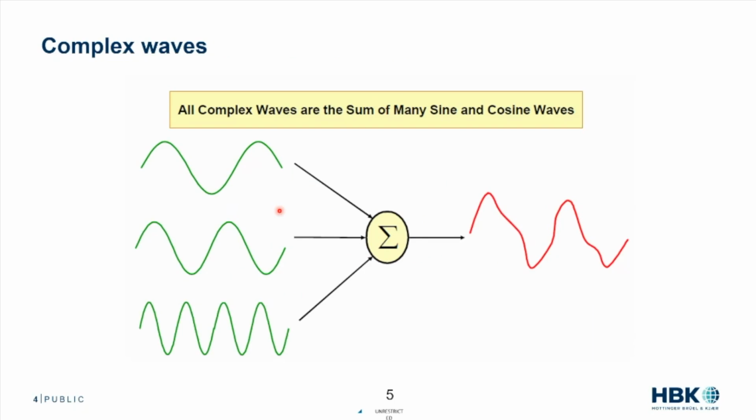So as many of you might know, electric motors have excitation that's sinusoidal. And I think it's really important to stress that we almost never work in pure sine waves. I'll probably say that a dozen times today. What we work in is a conglomeration of different waves at different phases and different amplitudes. We push all of these waves together and we get a complex waveform out. And this is a lot closer to the reality we deal with in motor excitation.